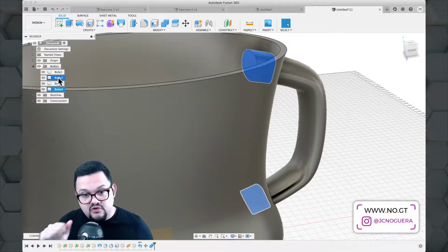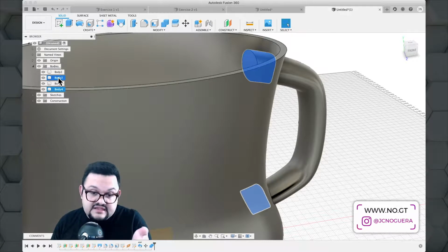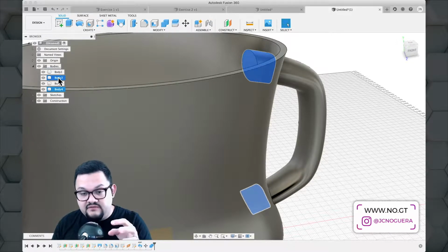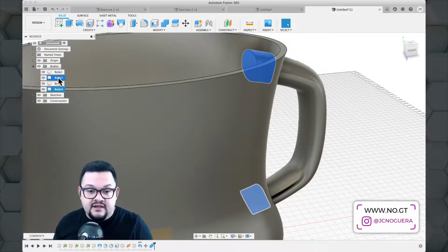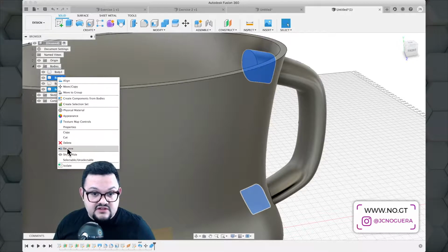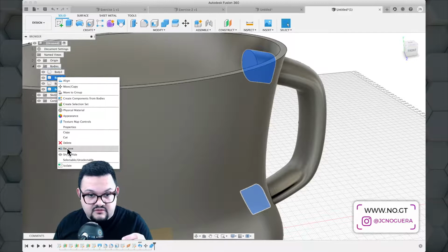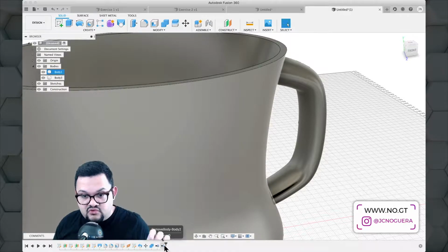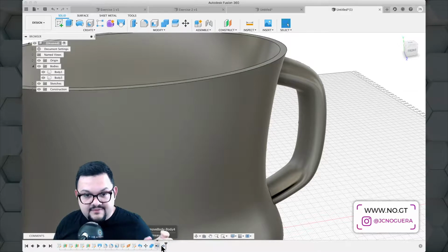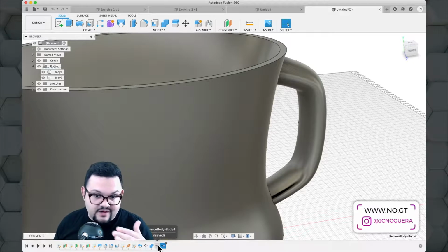Now, if you're removing objects from a scene in Fusion 360, deleting them will often cause problems. If you just delete the data, it might be that you're actually using these objects as a reference for other features further down your timeline. So the best recourse you have is to right-click them and use this function called Remove. Remove is going to remove them from your scene, but it's not going to delete the data. The object will remain in the scene, if you will. So if I click Remove, see how the Remove operation gets added to the timeline. You can unremove these objects by going back in time or by deleting the operation from your timeline. But for now, the objects have been removed.